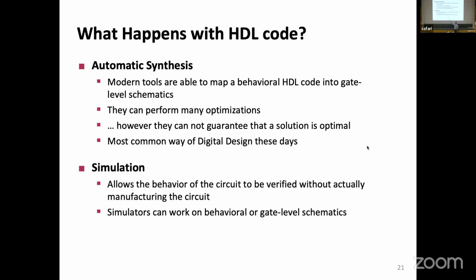Now, the other cool part is it allows you to simulate a circuit without building it. Because you know what's in there, AND gates, OR gates, flip-flops, latches, whatever, and you can just say, assume these are the inputs, let's wait a few seconds and tell me what comes out. So making a chip these days, a very modern chip, costs millions of dollars, requires 200 people to work, I don't know, 3 years. And instead of waiting all this time, you can quickly on your computer simulate what the inputs and outputs will be.